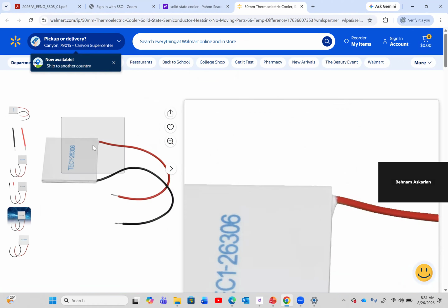Okay. And it's very good if you want to use it as a heat sink in a place that you can't put a fan. And actually, some of these car refrigerators that don't cool down very much, they are using this. Okay, if you use multiple of them and use a fan on the hot side, it's going to actually go down to freezing temperatures as well.